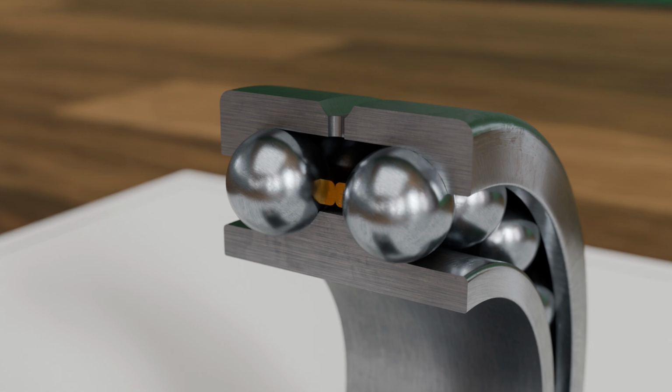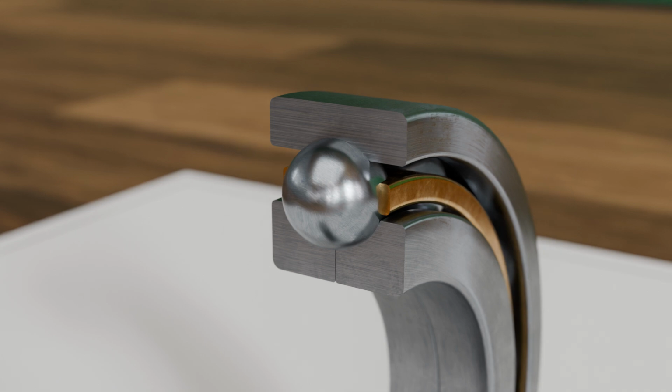A special design of single-row angular contact ball bearings that, similar to double-row types, can absorb axial forces in both directions is the so-called four-point bearing. The raceways are designed so that each ball makes contact with the raceways at 4 points simultaneously, which gives the bearing its name. In contrast to other bearing types, their ability to absorb radial forces is, however, very limited.